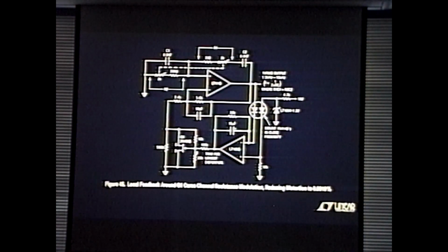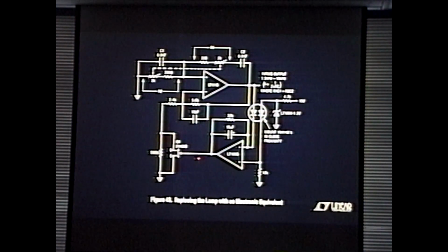That's channel modulating. What does that mean? What it means is, in this circuit, I'm using this amplifier's gate voltage to control the resistance of this FET. Well, that circuit will work. The problem is the FET's a fairly symmetrical device. That means the gate to channel voltage sets the impedance of the FET.